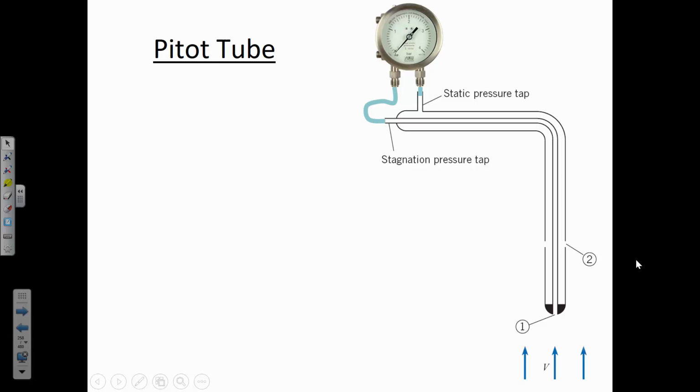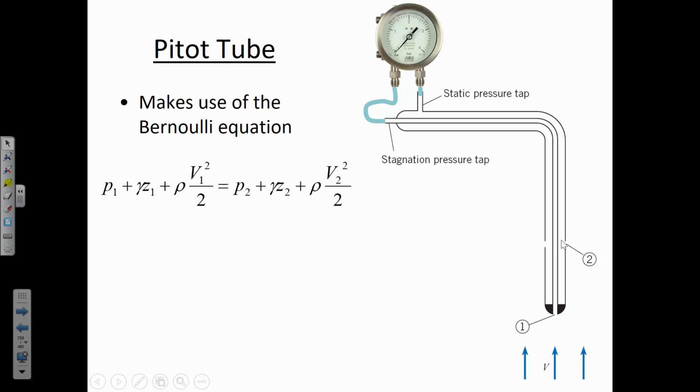And so that same idea that we had before in the stagnation tap, that there's some little extra amount causing the pressure to increase because the energy is transforming from its velocity head to additional pressure head, that's happening at 1. But at 2, there isn't the velocity head exchanging into pressure head. So let's apply Bernoulli's equation and look at what that says about this Pitot tube.